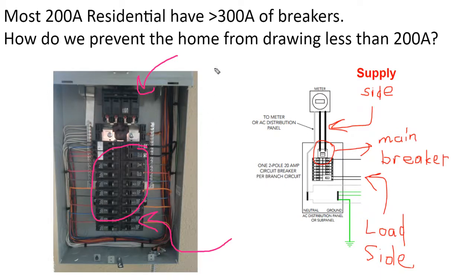Code allows the extra 20% amps capacity when solar feeds the very bottom of the bus bar, not because it's being nice, but because when solar is landed at the very bottom of the bus bar, the actual cross-sectional area of the bus bar that the current is physically traveling through will still not exceed 200 amps, because the electricity from the solar array will not combine with the electricity from the main power supply before flowing into the load, because in the exceptional case where you get the extra 20%, all of the load is located between the two power sources.